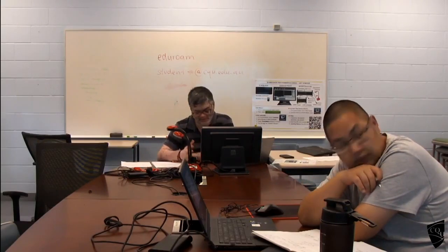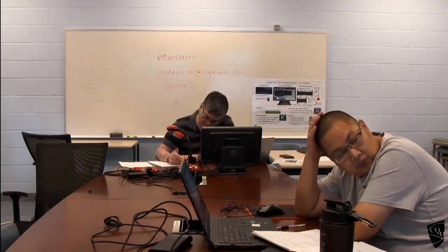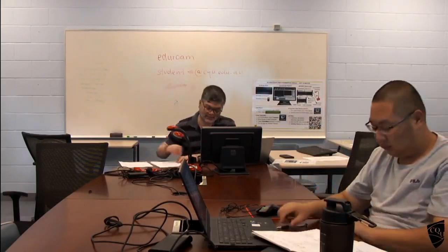Okay, for any different loadings or continuous or discontinuous, the number might be different. If you have uniformly distributed load, it is something like this. So this is the loading case. So for SLS, deflection normally is something like WL to the 4 over EI. Okay, so this is the format of the deflection.